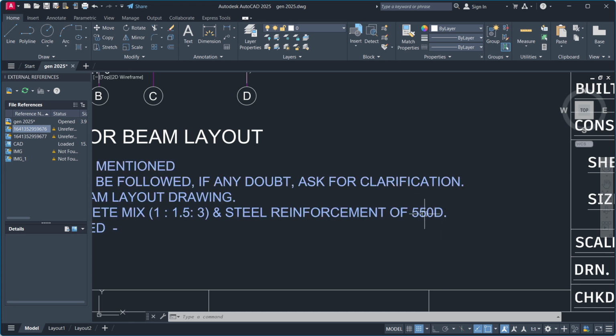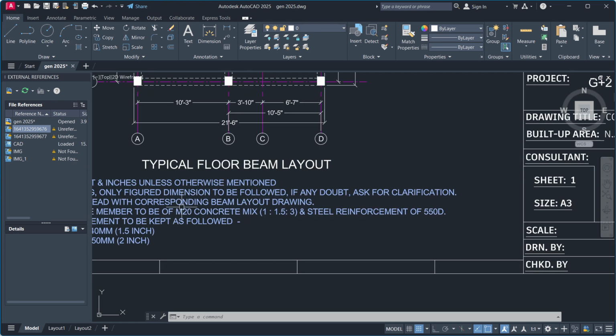So there are different grades of steel available in the market, like 415 grade, 500 grade, 550 grade. Even some companies have now come up with 600 grade of steel. Up to 650 they have gone, but I will use 550 grade. And then the ductile series also comes, like 500D, 550D, 600D, but I will use 550D. So I will define this material in ETABS.